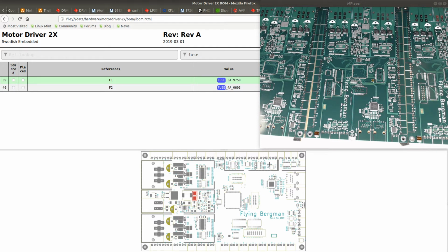And it's actually not an issue that the solder paste gets dry, because there is enough solder paste to be able to press the component against the solder paste so that it sticks to it. When I was doing this without a stencil, I had the problem that it was very hard to apply a good amount of solder paste to the pads, because it doesn't naturally stick to the pads. It needs to be pressed against the pads to stick. So without a stencil, it was hard to have enough solder paste so that components could be pressed into it. But with a stencil, it works really well.